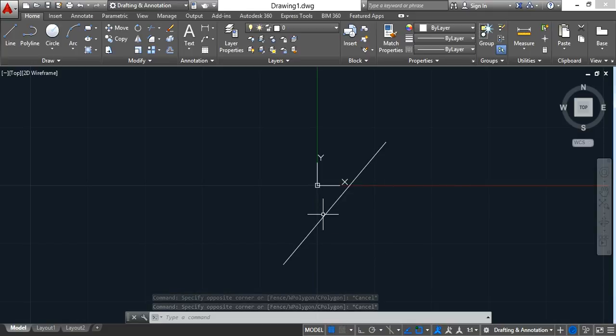If you also notice, I drew this slanted, and you might be wondering, is there a way to make this travel 90 degrees? Yes, that's what this button's for. There's ortho mode. You can also press F8, I believe. There we go, F8. Another thing is you want to attach another line to this. I can. That's your endpoint snap. That's your midpoint snap.